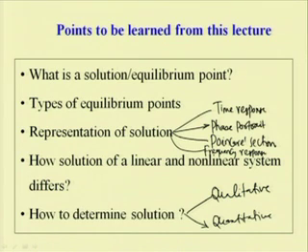So, in case of the time response, one can plot the response of the system with time, and in case of a single periodic or 2 periodic or quasi periodic or chaotic response, the time response will be different from one equilibrium point to the other. In case of the phase portrait, let x be the response of the system, then x dot is the velocity of the system. So, we can represent a phase portrait by plotting x versus x dot.